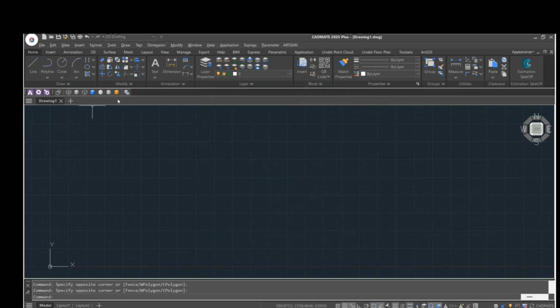And coming back to the editor window, I will draw a vertical line here. In order to define this as our symmetric axis, there is one more option here in the status bar called pick symmetric axis. So using this, I am going to pick this as our symmetric axis.